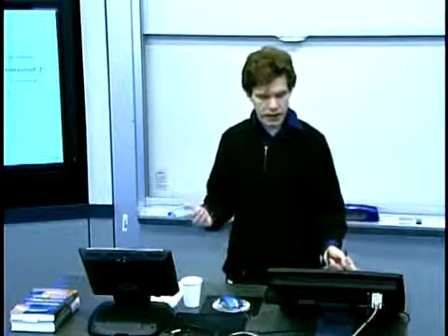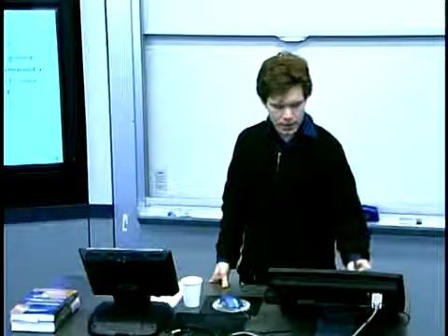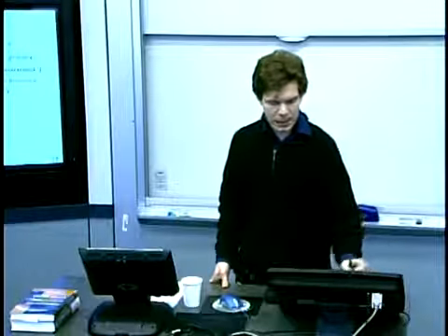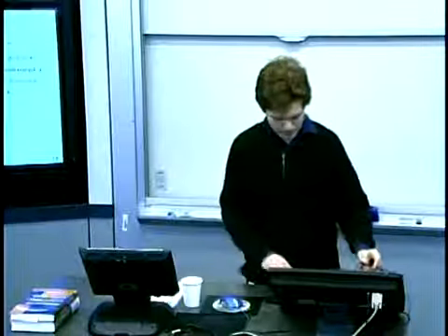Once we've done that, it's a simple step to go to the group variance. So this is an unbiased estimate of the group variance, the sum of the squares divided by the number of degrees of freedom in that treatment. So that's the number of parts sampled minus 1. And the minus 1 is because the value of the mean y bar sub t is dependent on all the individual y sub ti's. So there's one less degree of freedom than there are data points.